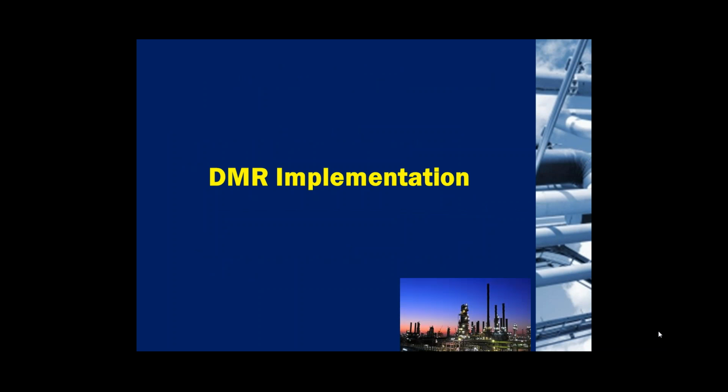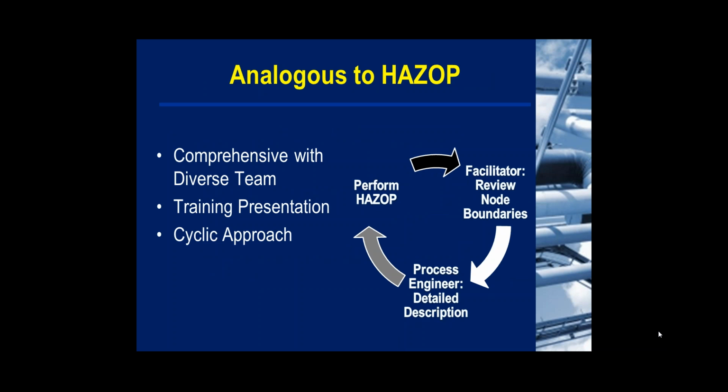Your second division, after looking at each one of your list of materials, you separate based off of operating parameter changes. The intent here is that potentially damage mechanisms are eliminated or increased based off of changes in pressure, flow, temperature. So what you can keep an eye out for are pumps, compressors, heat exchangers, where you'll see differences in pressure, temperature, and flow. Lastly, you have a mechanical engineer and metallurgist to provide input as far as damage mechanism nodes that might have too many damage mechanisms, and they might suggest separating that damage mechanism node into a few of them.